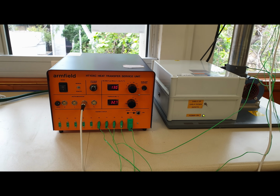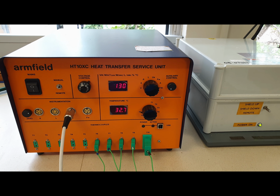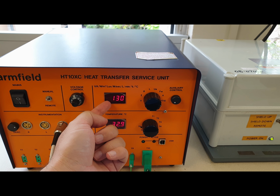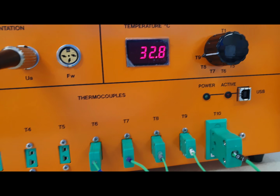Okay, 20 minutes passed. Let's read the temperatures. If for 1 minute the temperature didn't change, you can consider it a steady state. So let's read T10 first. As you can see, it's 130 degrees. Then let's start from T9.